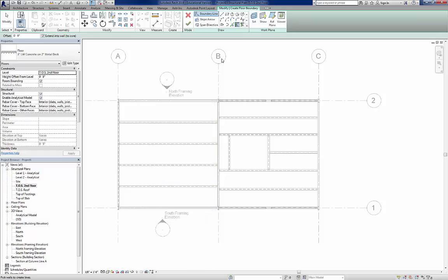Let's hit OK. Now we can go and hit pick lines. All right. We want to pick the outside edges of our beams. So 1, 2, 3. Now notice, since I picked this first one here, these additional lines show the span direction for what's going on. Okay, so these double lines right here, they represent the span direction for the major direction of our concrete.